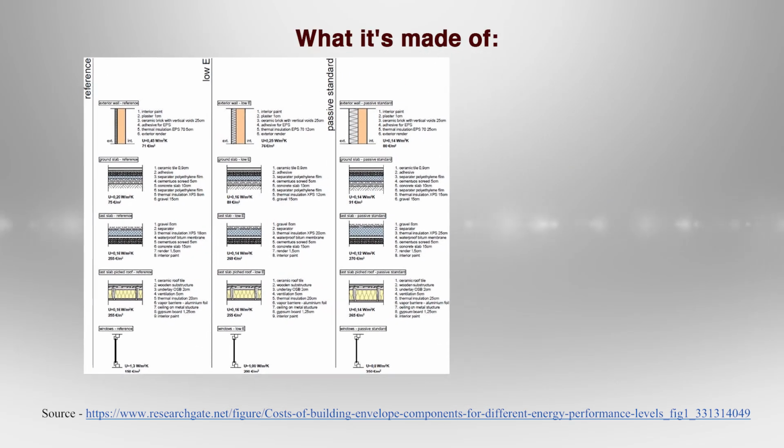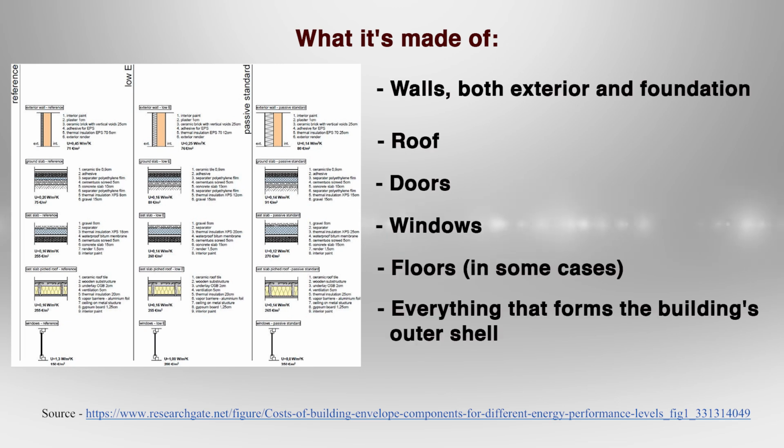The primary components of a building envelope include wall, roof, window and door, foundation, air and vapor barriers, sealants and flashings. Its main functions are to maintain indoor temperature by reducing heat loss in winter and heat gain in summer, preventing water infiltration and managing humidity level to protect the building structure and indoor air quality, minimizing air leakage to enhance energy efficiency and occupant comfort, providing the necessary support to withstand environmental loads such as wind, snow and seismic activity, contributing to visual appearance and design of the building.